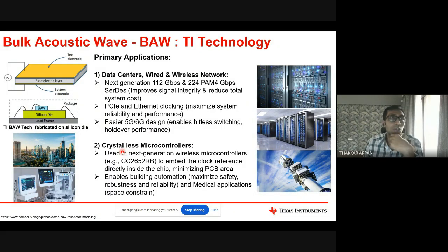So what we have is, usually it is taken care of by the power supply and ground routing, and through the substrate. Mostly the leakage happens through the substrate of this silicon die, and then power supply, because you are sharing power supply and ground for different modules. That's how it gets coupled. So basically any clock coupling, right, there are two mechanisms. One is electrical coupling and one is magnetic coupling.